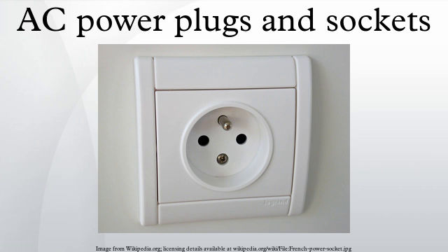Israel SI32. The plug defined in SI32 is unique to Israel. There are two kinds, one with flat pins, and the other with round ones. The pre-1989 system has 3 flat pins to form a Y shape. Line and neutral are spaced 19 mm apart. The plug is rated at 16A.